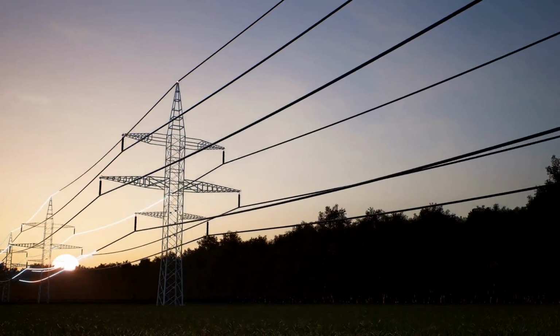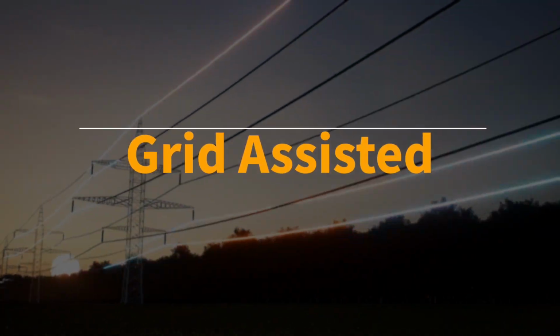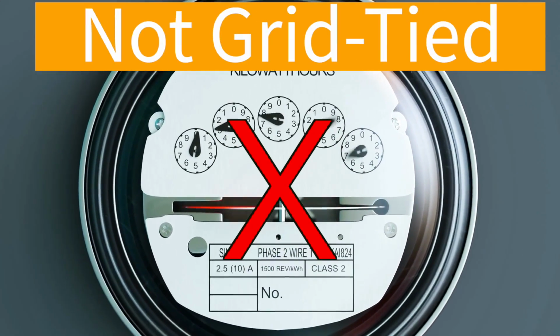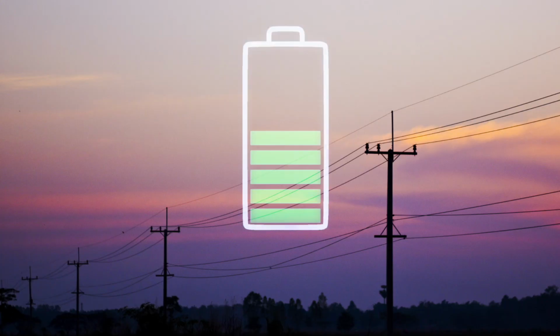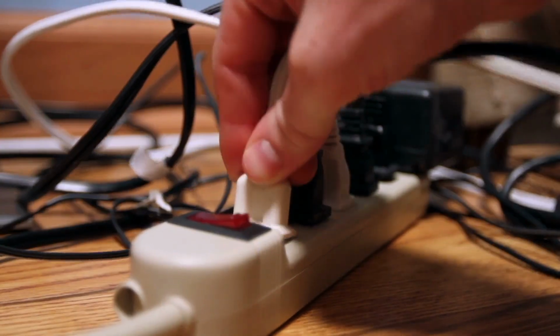Okay, so let's design a system that uses AC from the grid as an input. This is known as grid assisted. It is not the same as grid tied, which means you can sell power back to the utility company. But we can use the grid for several reasons. We can run loads when our battery is low. We can charge the battery with the grid power. We can use the inverter as an uninterruptible power system. In other words, run the loads on the grid power most of the time with a battery backup just for